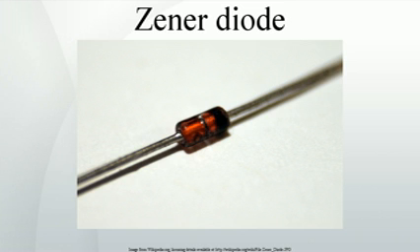Another mechanism that produces a similar effect is the avalanche effect, as in the avalanche diode. The two types of diode are in fact constructed the same way and both effects are present in diodes of this type. In silicon diodes up to about 5.6 volts, the Zener effect is the predominant effect and shows a marked negative temperature coefficient. Above 5.6 volts, the avalanche effect becomes predominant and exhibits a positive temperature coefficient. In a 5.6 V diode, the two effects occur together, and their temperature coefficients nearly cancel each other out, thus the 5.6 V diode is useful in temperature-critical applications.